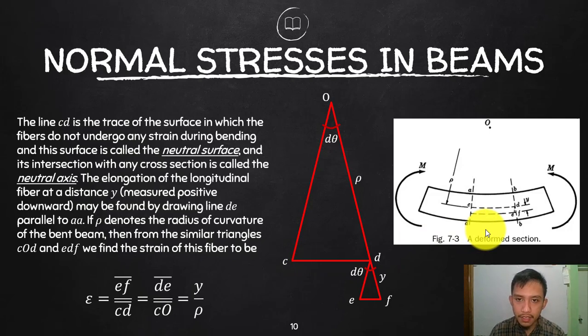So let's say now that is a triangle. We can approximate that as a triangle from point O to C to D. So OCD, and that is your radius of curvature, which is your rho. And then let's consider somewhere here in this parallel surface, which is under tension, the points E and F. I will consider that is just a continuation of your radius going to your point F, intersecting the parallel fiber, which is under tension.